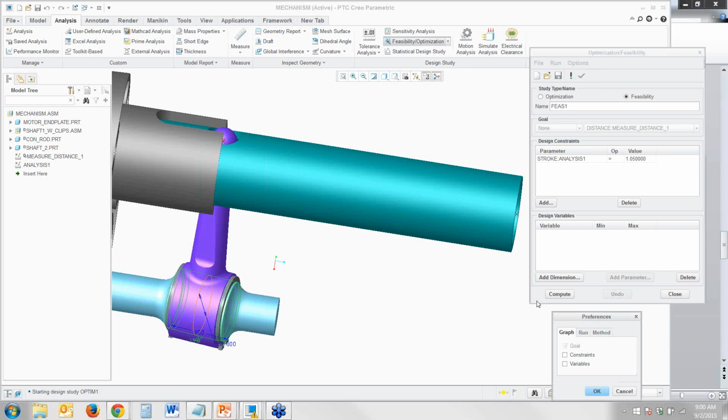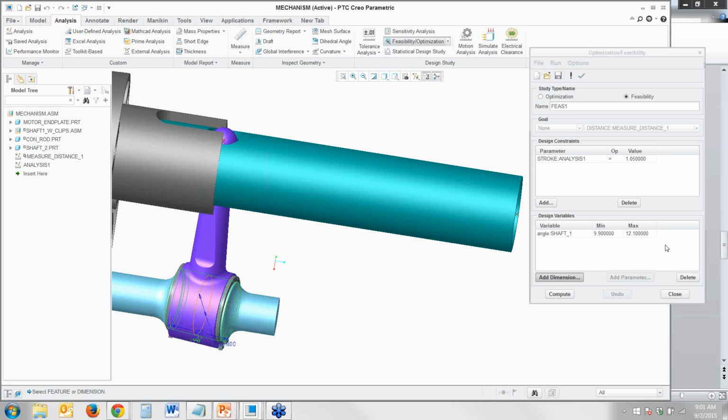And I'll also then go here and set my run convergence to 0.001, because I want one that's really, really accurate. And so I want to make sure it really converges. And then we'll add that dimension to it. So that value, and we'll say go anywhere from 4 in this case to 16.